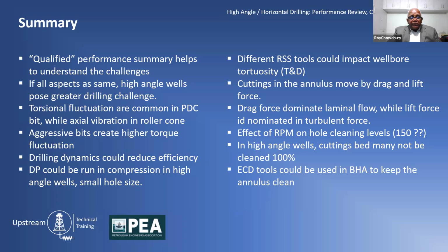Okay, Muhammad Zubair asked me a question again. Can we use a roller reamer when drilling horizontal in the coal seam? Unless you have some sort of experience, I will avoid using anything that interacts, because you already have a stabilizer or two. Adding extra, unless you have a torque issue that you are handling, can we handle that with the drilling fluid?